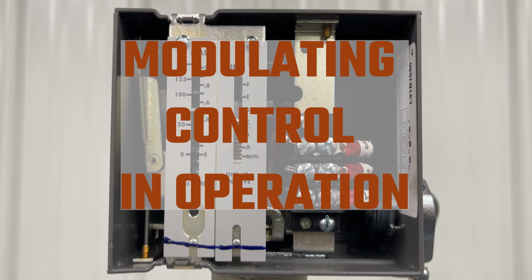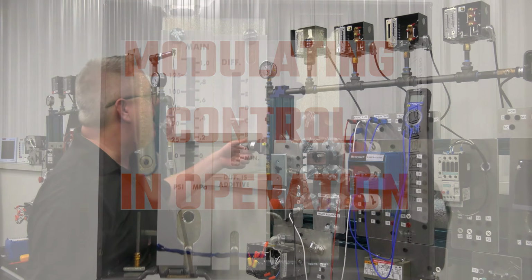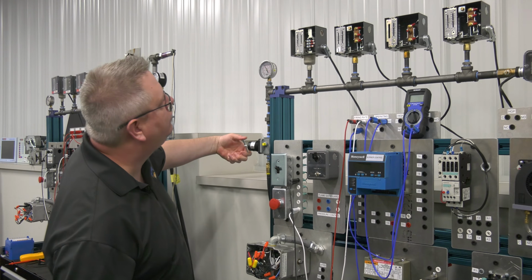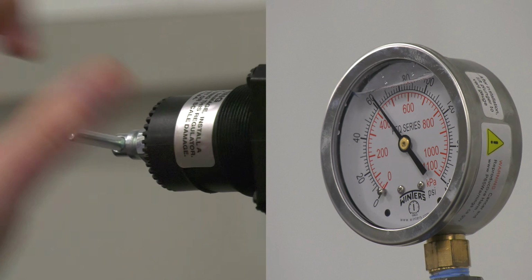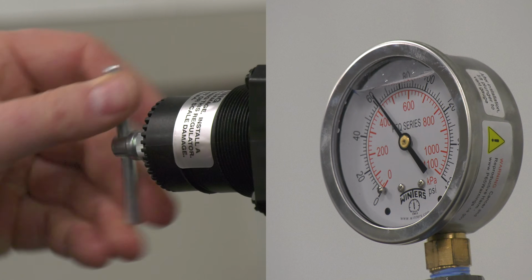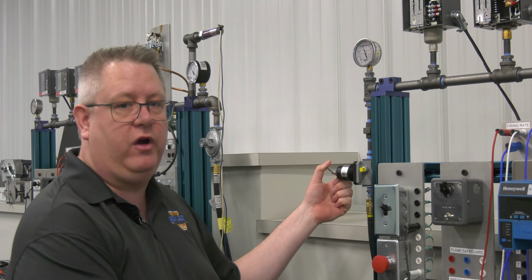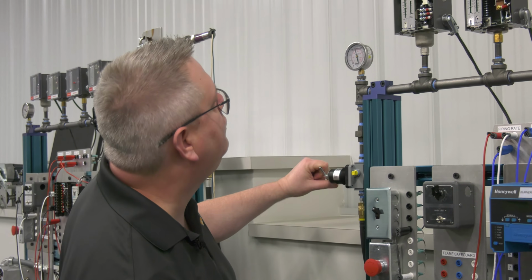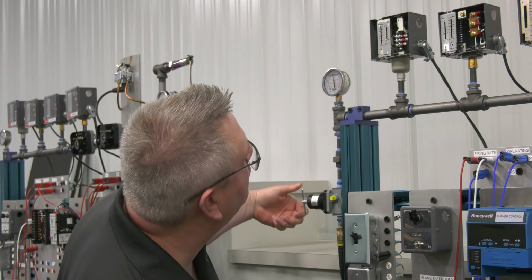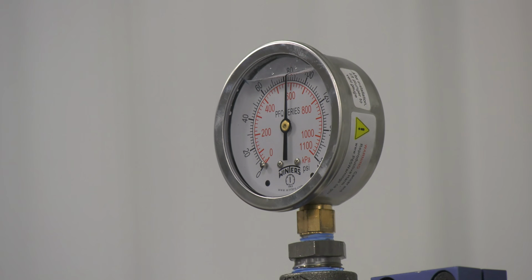So let's take a closer look at the modulating control in operation. I'm going to go ahead and apply pressure to the switch and watch that potentiometer. And as soon as that comes off the high fire end of the potentiometer, what we'll see is our Modutrol motor starting to drive to its low fire end. As the pressure continues to climb, that needle will continue to move until it hits the end of its travel.